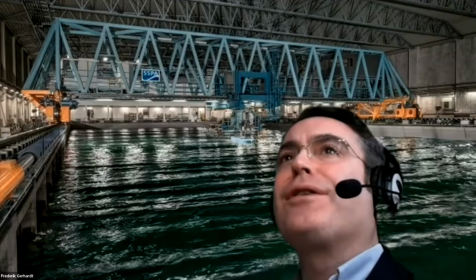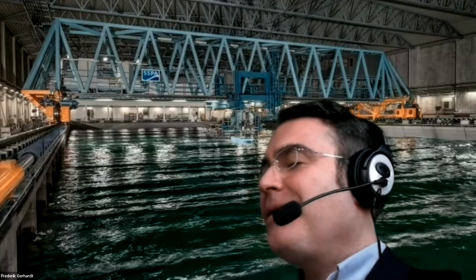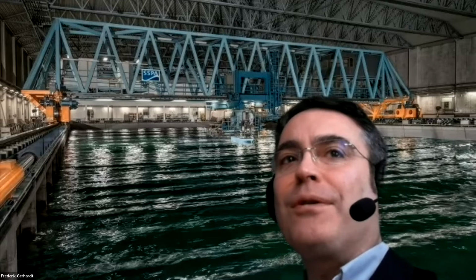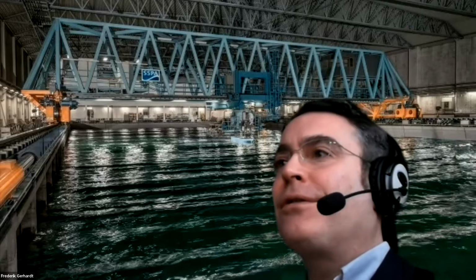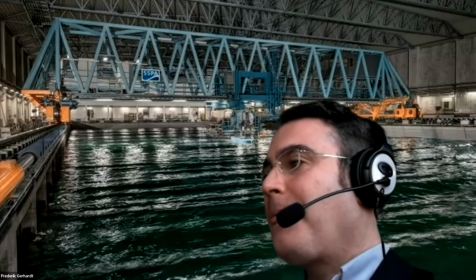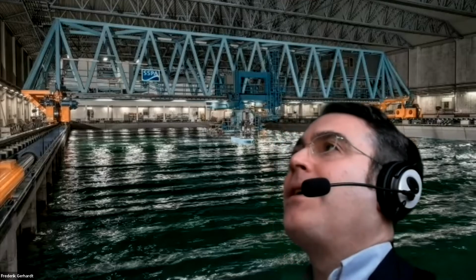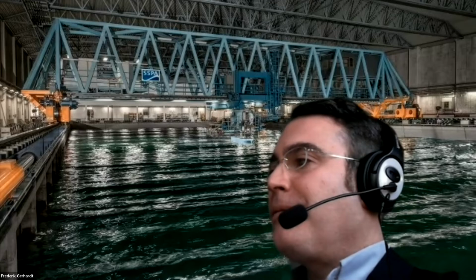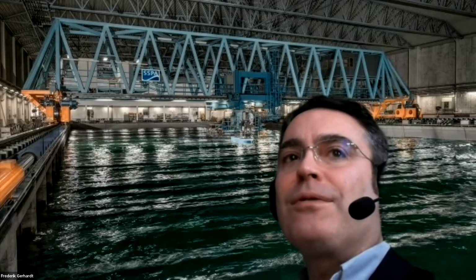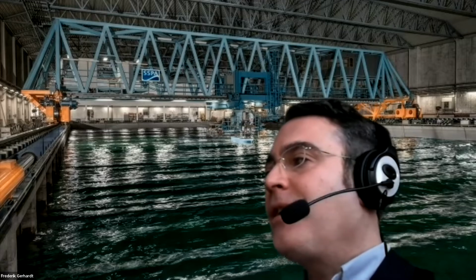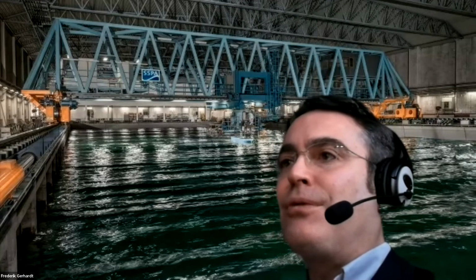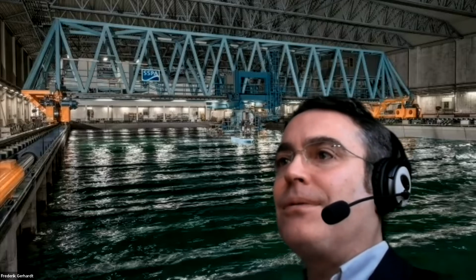Yes, I can comment on this. It is obviously very challenging to model this explicitly with a physics-based model. But I think what you can do is find out what the limiting conditions for your ship are, and now it's a kind of captain experience again. You say, okay, waves so and so high are critical, and from the wind propulsion system manufacturer, the maximum forces and maximum wind speed for the system are so and so much. So you start setting up what we call a risk layer for this digital twin. And you say, if I'm outside of my safe operational envelope, I need to do something. I need to reef or change course or turn off the rotors, or just simply do something.